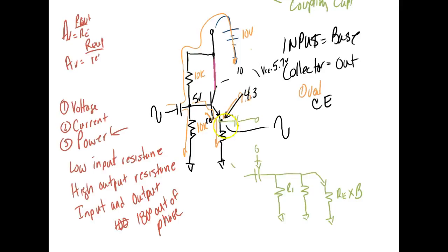But what we're going to do is this resistor over here is going to be really small. And this is where you'll connect your speaker. Normally on this guy, we'll come up here and actually put your speaker coil right there. It's actually in the emitter, so we don't have to output it. We'll look at it later on. And these guys here, standard home speakers are 8 ohm speakers.